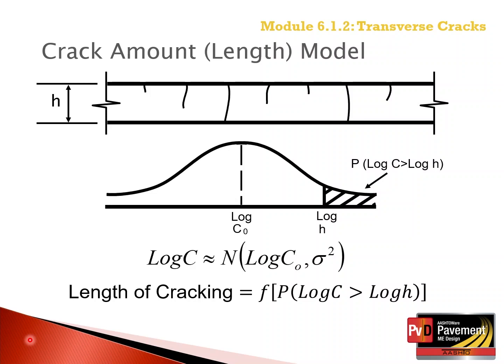In addition, the definition for when a predicted crack becomes a real crack that can be observed and measured at the surface is empirical. The definition of a crack calculated by the model is when the tip of the crack propagates through half the asphalt layer thickness of the entire asphalt layer thickness included in the simulation, not just the asphalt wearing surface.